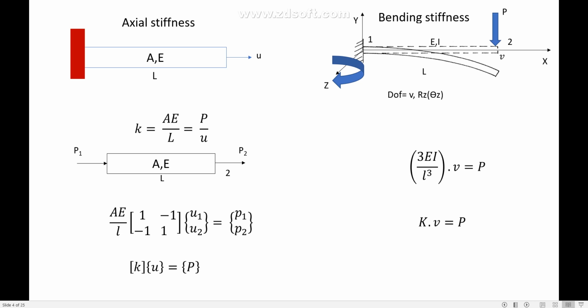Now, as you may know, the bar element is a pin joint and can carry only axial force. It can be used in modeling a truss; wherever we have a truss system, we can use it. It has a property EA, known as extensional rigidity. If E multiplied by A is high, the deformation will be very small.